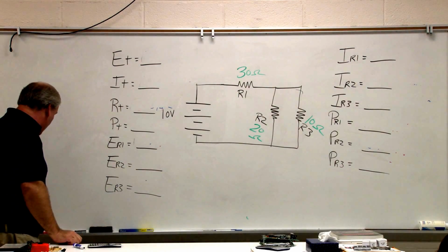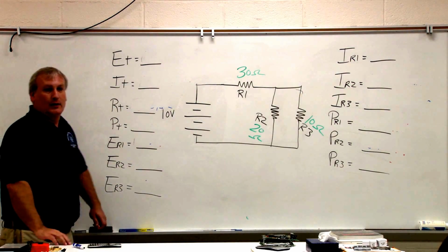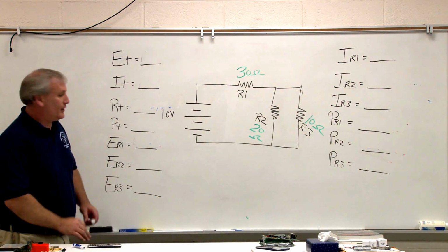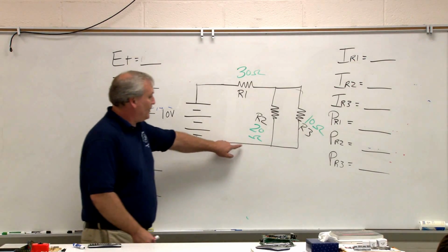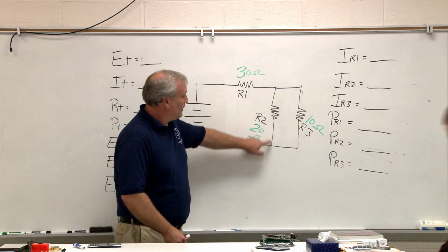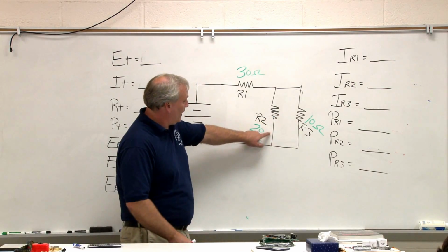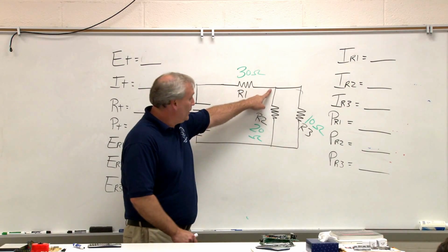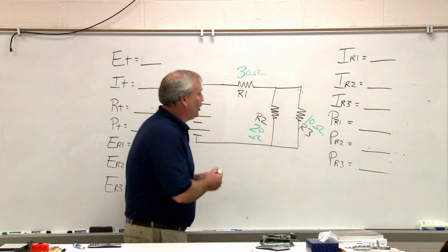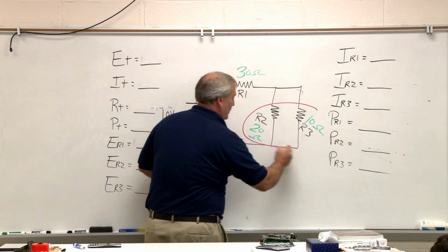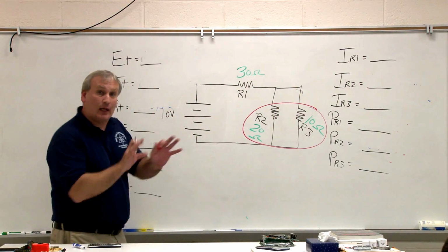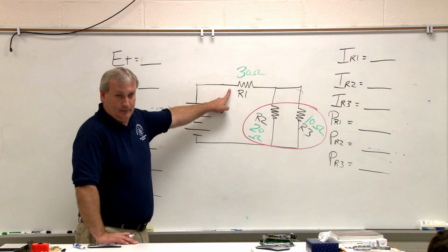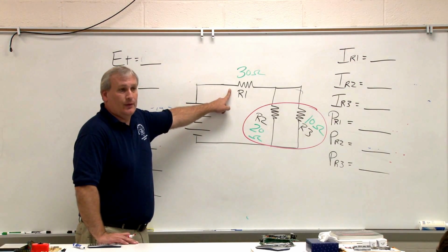Okay, so we are going to determine which resistors are in parallel and which resistors are in series. How do we do that? Magic. Follow my electrons. Seth, what's happening here? Okay, exactly. So I got 2 paths here. I can go through R2, I can go through R3, and then they meet back here. So we have a 20 ohm and a 10 ohm resistor in parallel. So we've identified and isolated our parallel. We now have that in series with R1. There's no other series resistors.